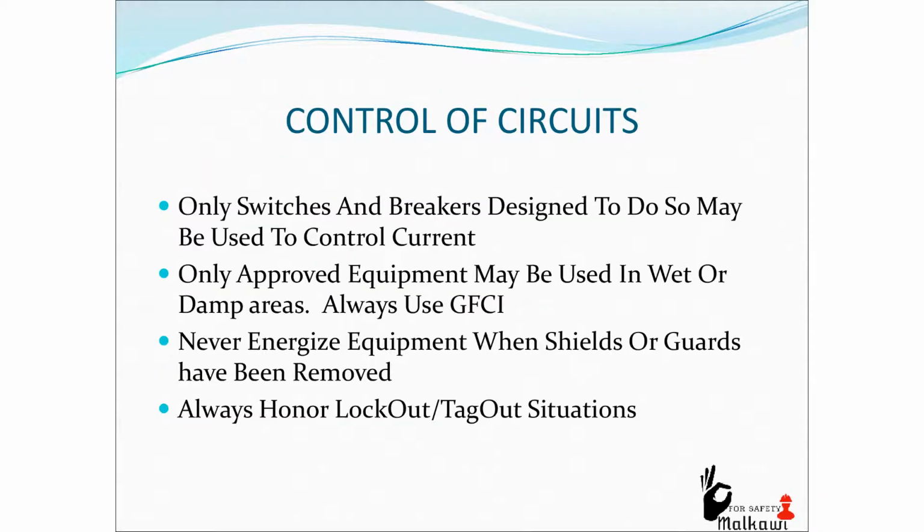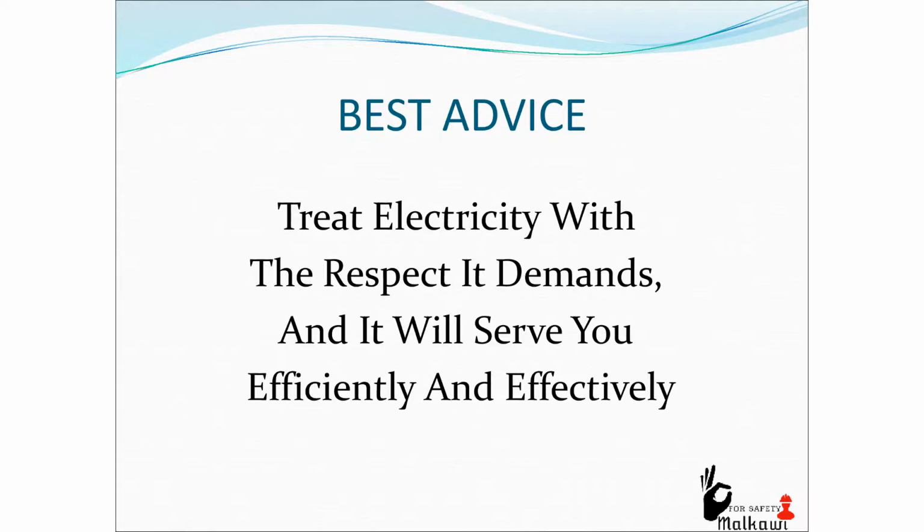Control of circuits. Only switches and breakers designed to do so may be used to control current. Only approved equipment may be used. In wet or damp areas, always use GFCI. Never energize equipment when shields or guards have been removed. Always follow lockout tagout procedures. Best advice: treat electricity with the respect it demands, and it will serve you efficiently and effectively.